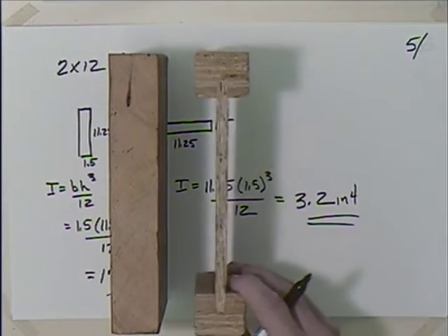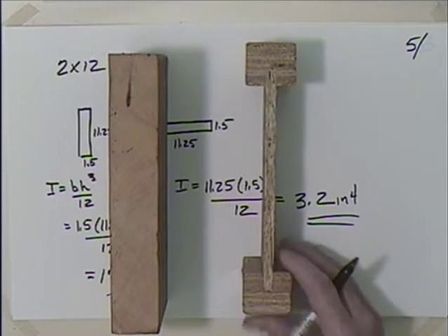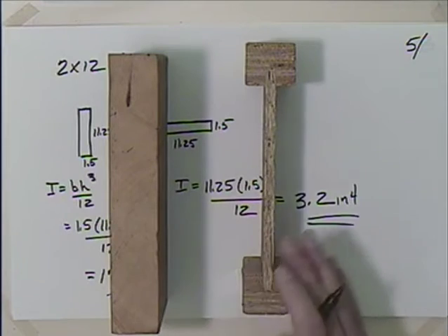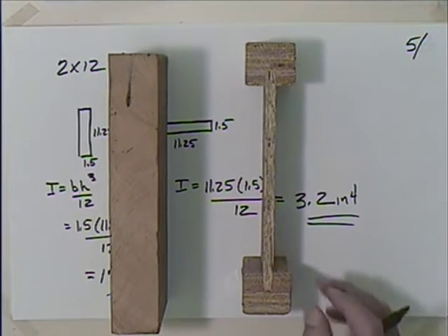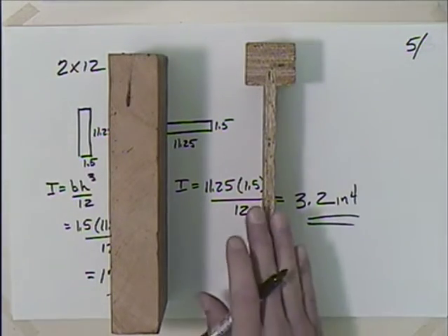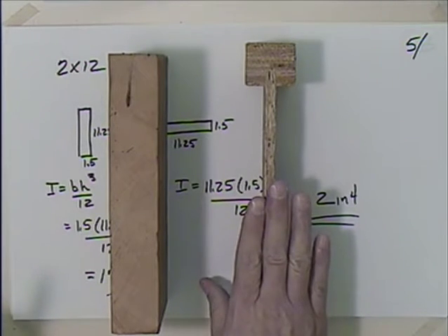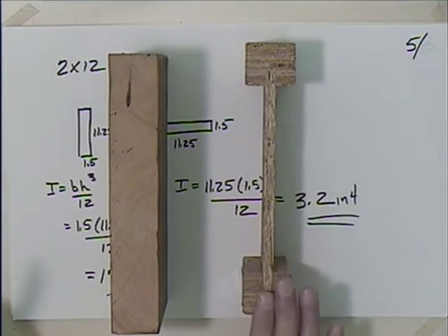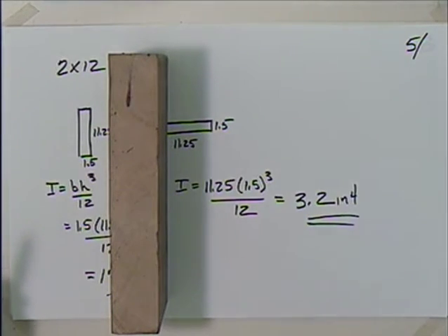Now, these are about the same height, but so this one is going to be weaker than this one, but pound per pound, this is going to be a lot stronger because it's a lot more efficient cross-section. And if we allow this to be slightly taller, we'd probably get something that is as strong or stronger than this piece. So some things to think about when you're doing that. When you start looking at the area moment of inertia, a section like this is a very efficient section.